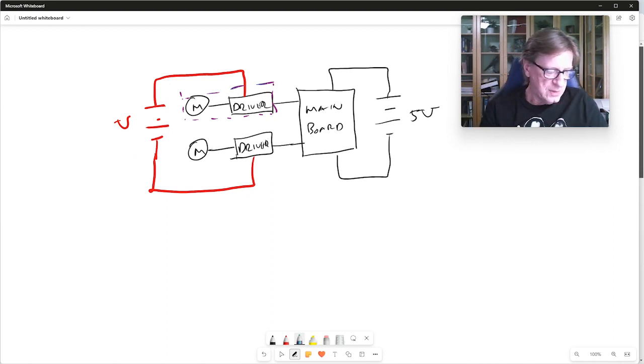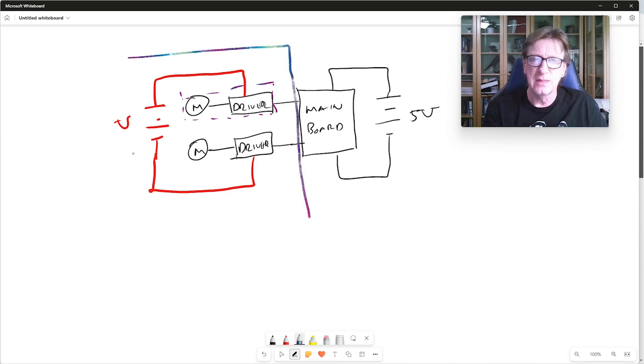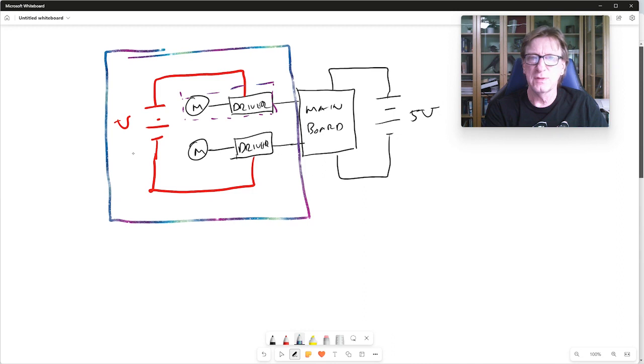All right, so let's figure out how much voltage we're going to need for this. We're going to start the same way that we've done before, but right now, all I need to worry about is this part of the circuit. I don't actually care what's going on with the main board side because it's got its own battery pack. The battery pack that we're going to use here, what we typically use in lab, is actually the same one that we use here. So that's going to be 6 AA batteries. So that's going to provide a maximum. Remember, each AA battery is 1.5 volts.